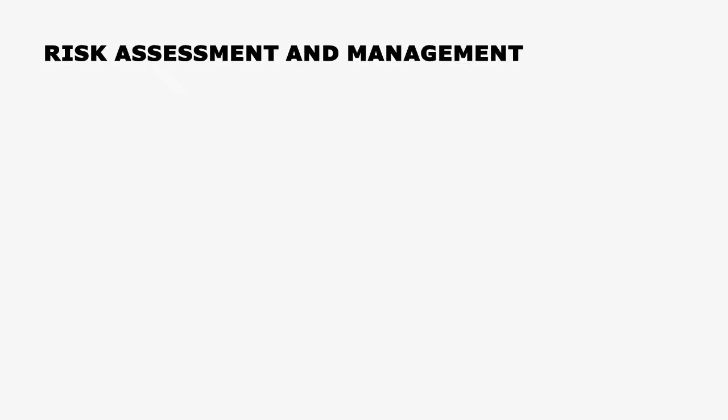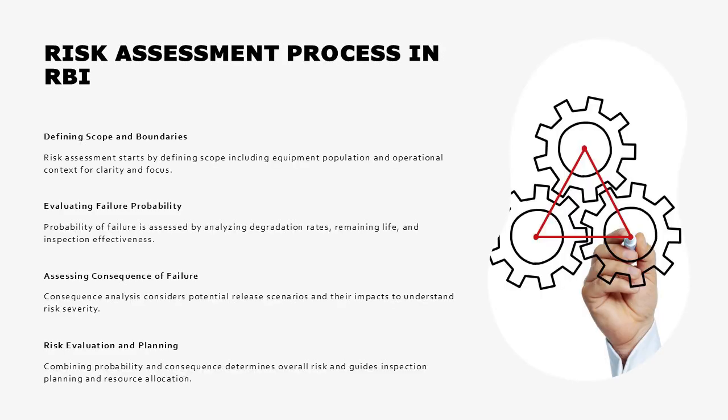Risk assessment process in RBI, risk management and risk reduction. The risk assessment process in RBI follows a structured sequence designed to ensure consistency and technical rigor. The process begins with defining the scope and boundaries of the RBI assessment, including the equipment population and operating context.